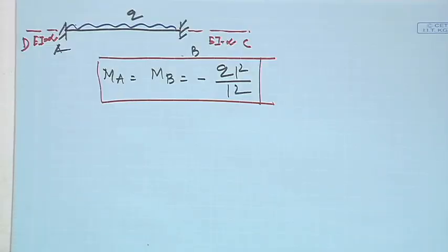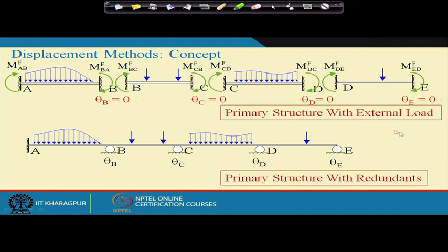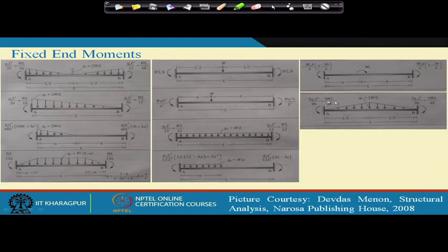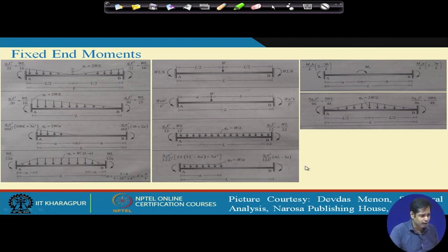We know how to solve statically indeterminate structures using the force method. So, you can apply the force method to get the corresponding fixed end moments. Now, these are already available in the book, but do not take these values for granted. At least once you should compute the fixed end moments for different loading conditions, and then see whether the moments you are getting match these values.